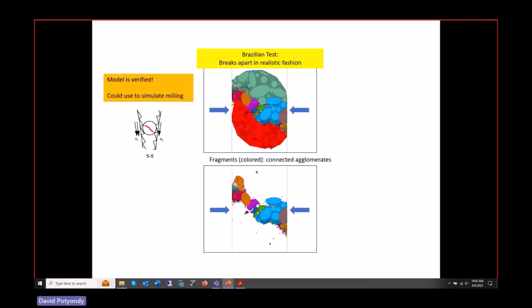And so they're in the process of developing a special chemical pre-treatment that will go inside the endosperm before the milling. And what it will do is preferentially attack the interface of the starch protein. And so basically they can selectively weaken that interface. The idea is if you weaken the interface enough, hopefully the starches will break free from the proteins.